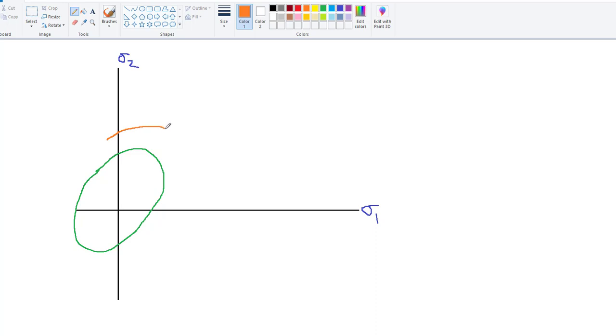One of them is isotropic hardening, and that's essentially where the yield surface just grows uniformly in all directions. This would be considered isotropic hardening, and this works for monotonic loading, meaning loads that aren't reversed and cycled. So this will not capture the behavior that we just saw.